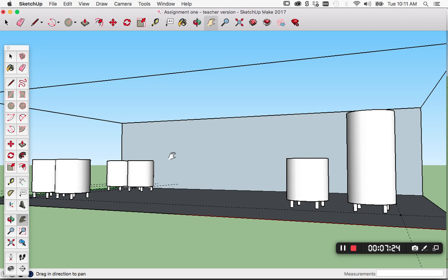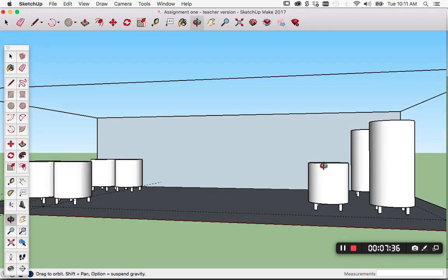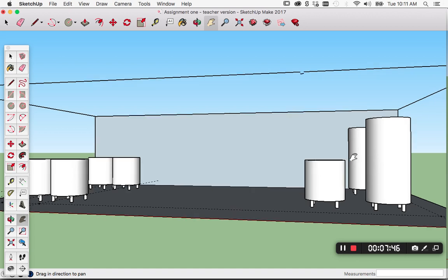So in that case, the static head for the overall system that the pump needs to overcome is just 2 meters. It's just the difference in height of the liquid level in the supply tank and where it's going, which is at 4 meters. So the minimum static head would be 2 meters, the difference between here and here.